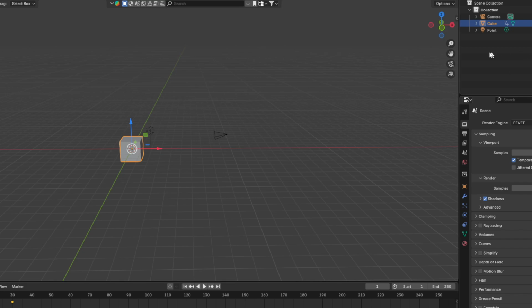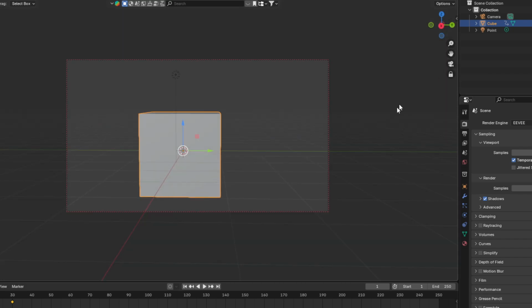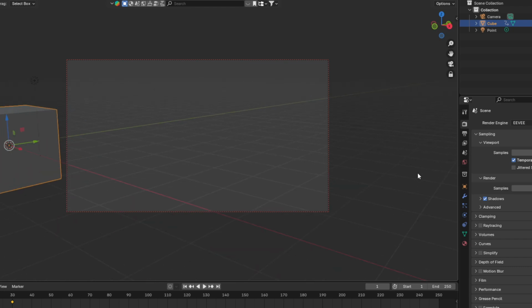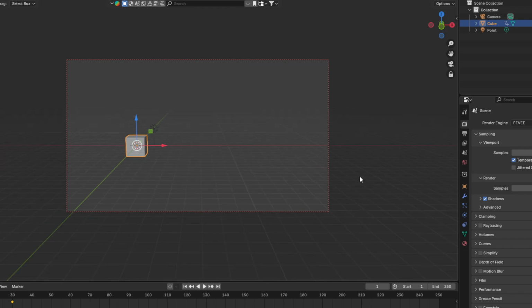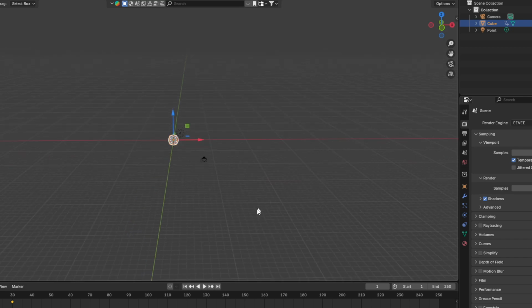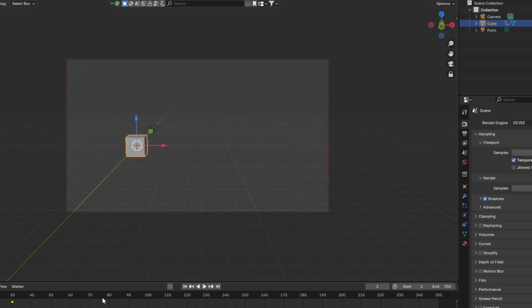my scene. And if I render this, I'm clicking my camera view from this symbol, and I'm moving from here. Let's try this perspective, and if I press the space button, my animation will also start. I'm pressing the space, and done.